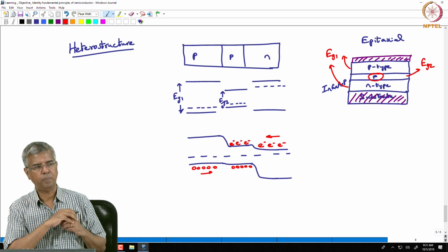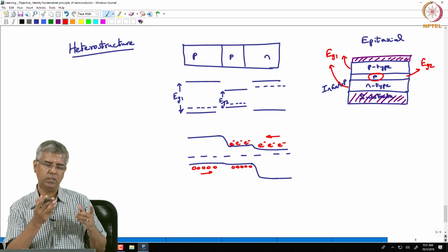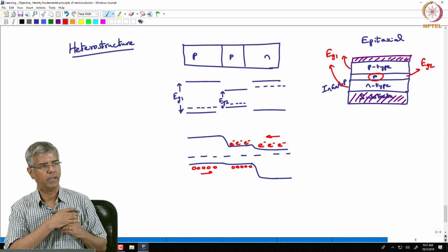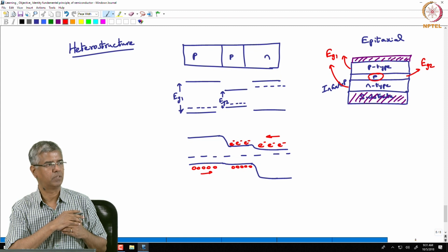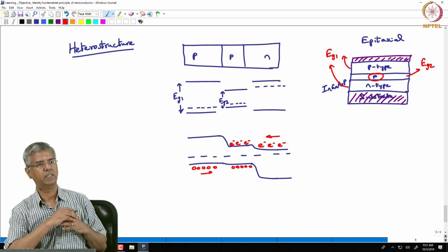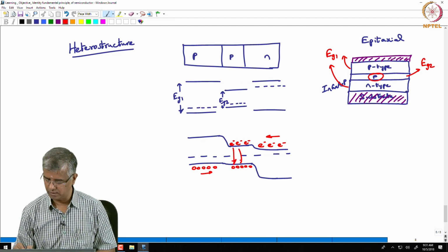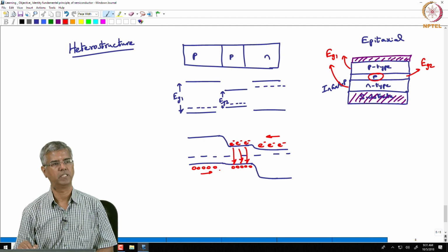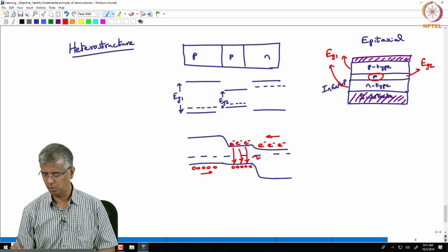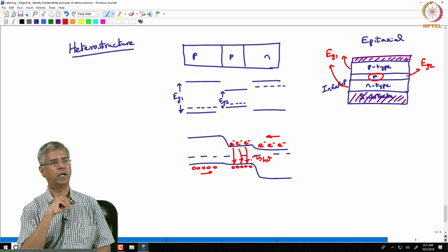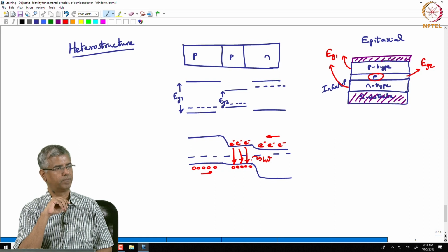And at that p-type region, it has nothing else to do but to recombine between themselves. The probability of recombination increases quite a bit in this sort of structure. So then in this region you have all this recombination happening, and because of that you have light emission.